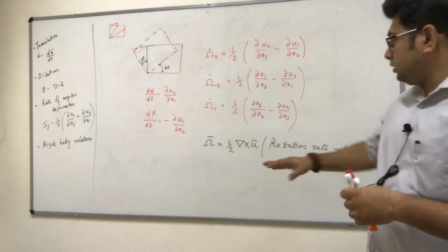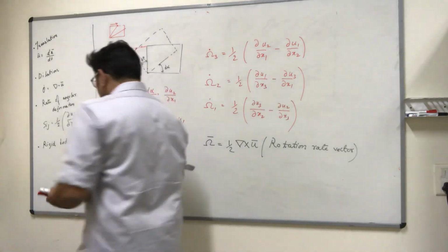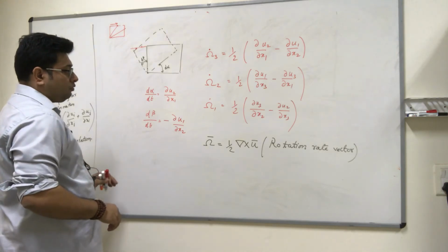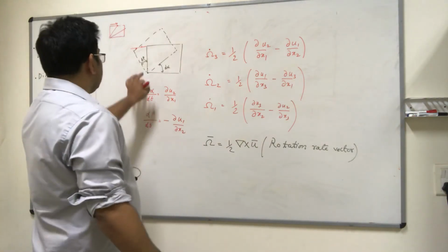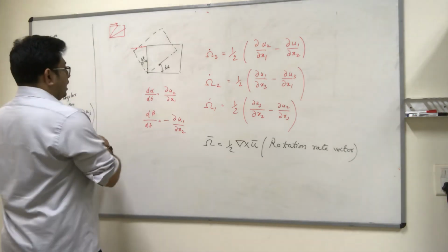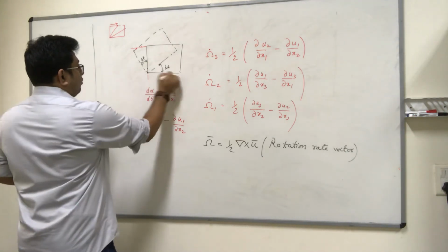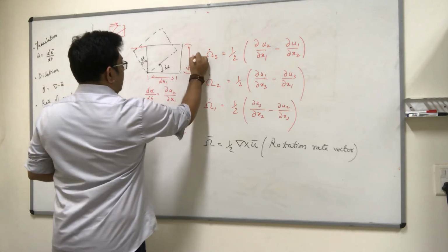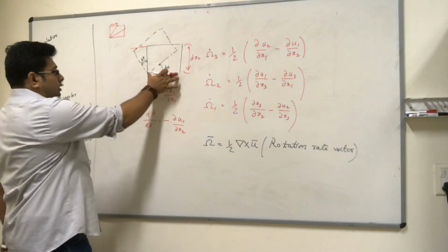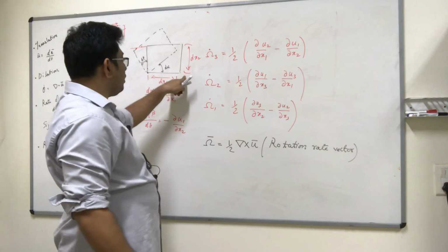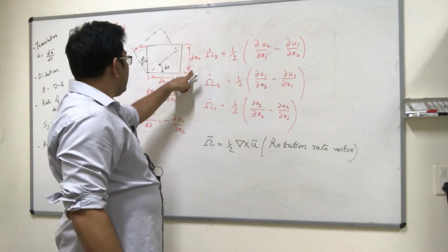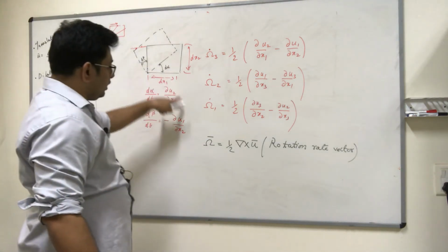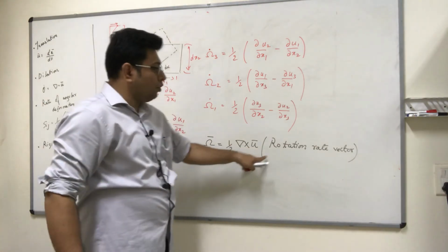And so in a sense we have finished the final deformation of your infinitesimal volume. These are all infinitesimal, remember. So these are dx1. If you look at this, these are not control volumes, these are fluid particles, and we have covered all their deformations, and finally the rotation, which is given by the rotation rate vector.